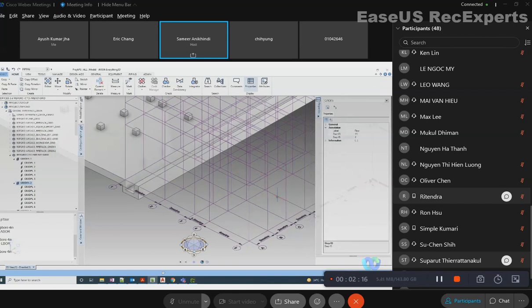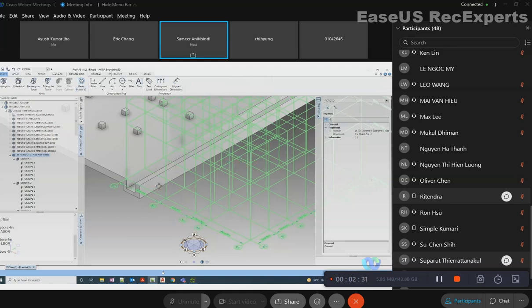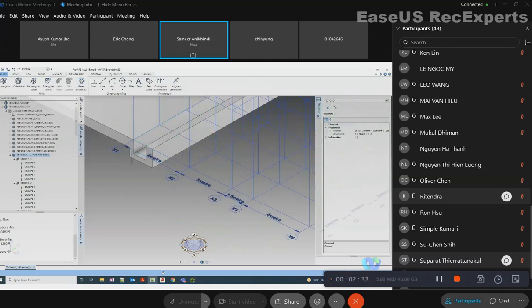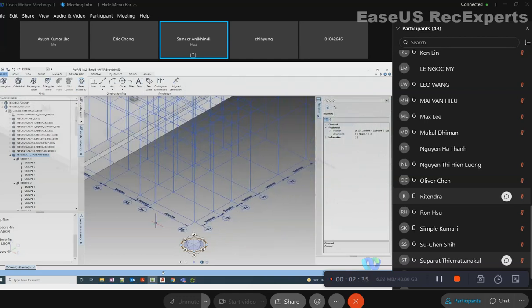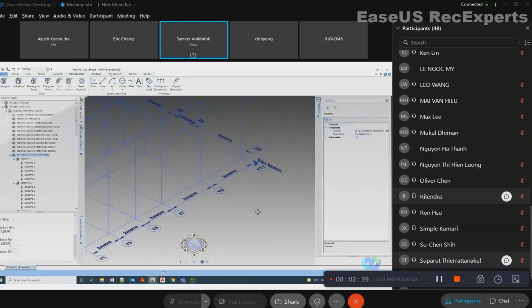Now, how to reset? Once you have set these values, you can select anywhere in the grid and go to design, reset plane ID. Click anywhere on the grid, reset plane ID. So you can see X2, the increment of 3, Y1, Y3, Y5, Y7, and so on.